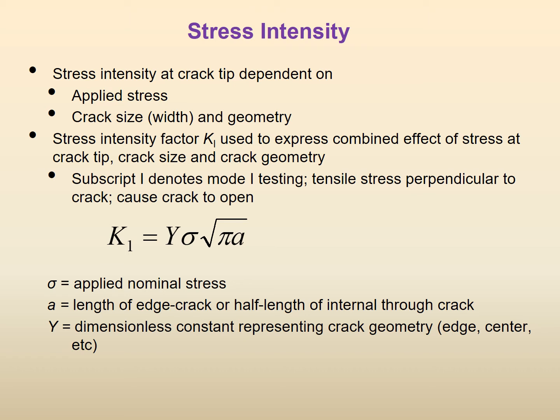So we have already done this, right? Stress intensity, this equation we introduced last time, but we talked a little about it. We said that this is a stress intensity K, Y is some factor, sigma is the applied stress, pi is pi, A is the crack length.